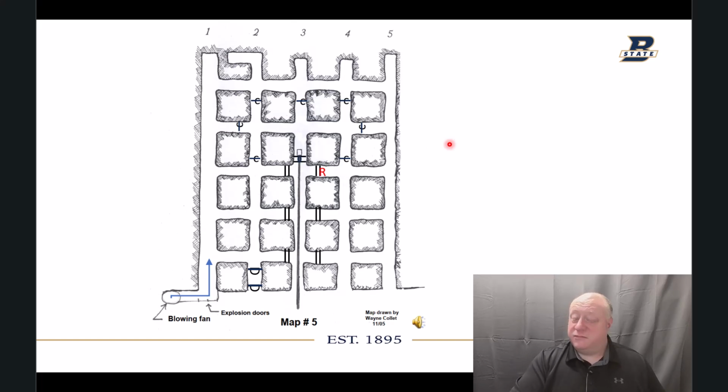But anyways, the next thing is, now that we have this air intake coming up this side and returning back down this side, we need to ventilate the faces, right? We've got to get air up into here, and we're going to show how we would hang curtain, because that's the way these are. I haven't seen a problem yet with vent tubing. We'll discuss it too, but we're going to talk about this first. We're using curtain, and we'll have to ventilate those faces, okay?